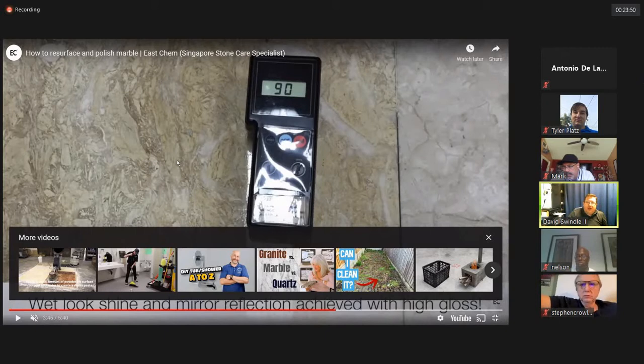Marble and granite are very similar. The process is pretty much the same for gloss restoration. You'll find that you will more likely have to restore gloss on a marble floor than you will a granite floor. Granite floors are so hard that they don't scratch real easily, so it's not often that you have to go in and do it. You may have to if the customer is careless.